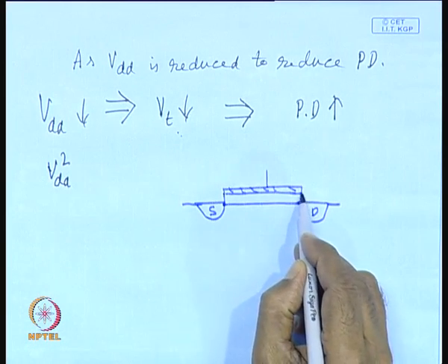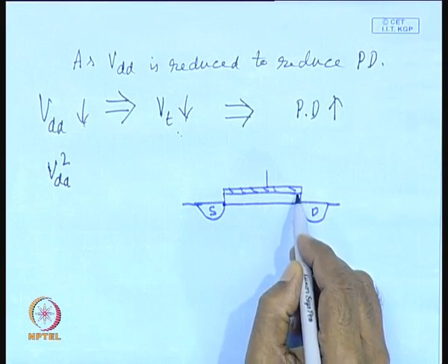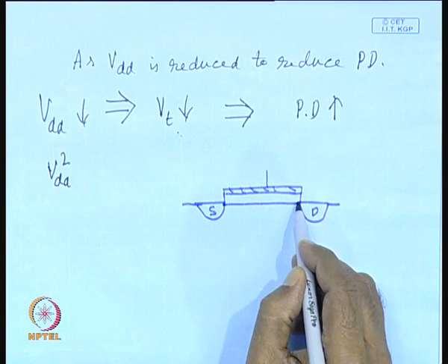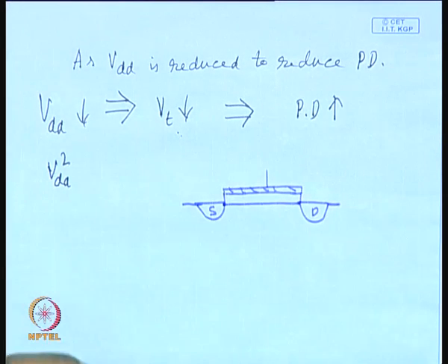So, this thickness of the silicon dioxide plays a very important role in deciding the threshold voltage. So, it is a common sense that smaller is the thickness, you will require lower voltage to create the channel region, and larger the thickness, you will require larger gate voltage to create the inversion region in the channel.